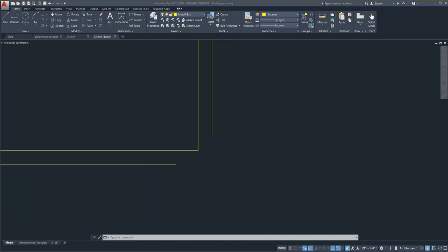All right, so let's talk about how to achieve those, all right? So the fillet command, if I type F, enter, okay? The way that we specify that radius is by clicking on radius right here. I could also type R, enter. So the current setting, which is seen right here, says the radius is 0, okay? So what that means is that if I select line number 1, click, and line number 2, click, I get a squared off corner, okay? Radius of 0 equals a squared off corner.